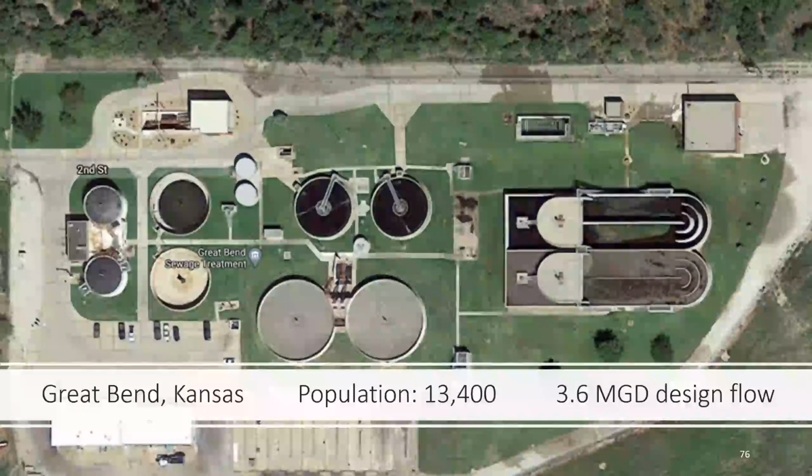You don't need it anywhere near that many times. You can stretch those cycles out if you want to. Stretch either air on or air off, because the wastewater is going to have plenty of time to get aerated for ammonia removal and plenty of time. If you only have 3 or 4 hours hydraulic retention time, those are too long of cycles. So in adjusting it, you want to maintain ammonia removal while improving nitrate removal. And improving nitrate removal means air off cycles, and maintaining ammonia removal means maintaining your air on cycle so you have a positive 150 millivolt. So my guess is you have a lot of room.